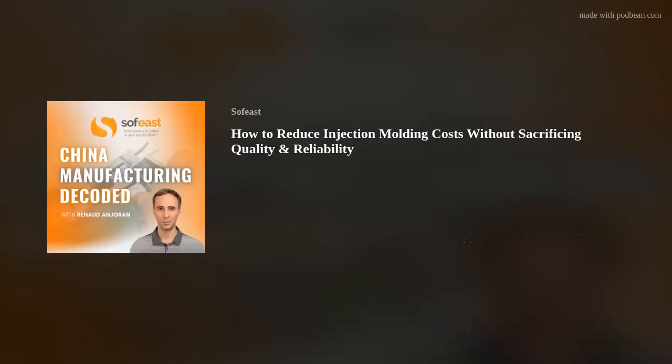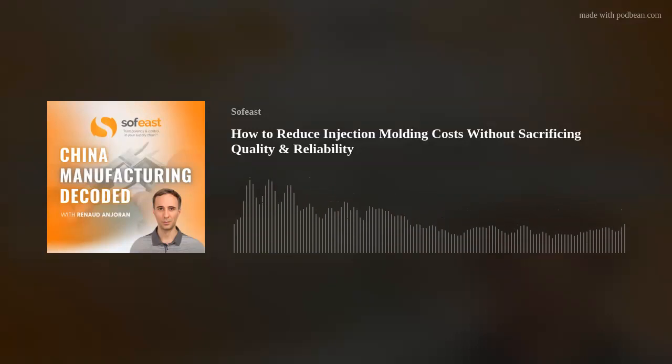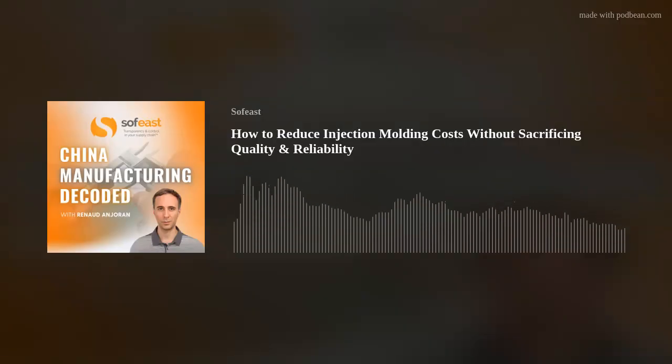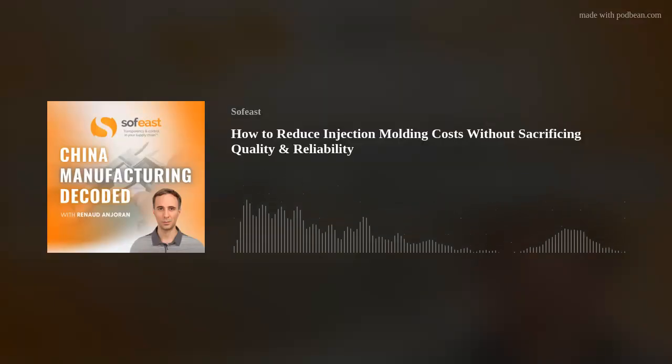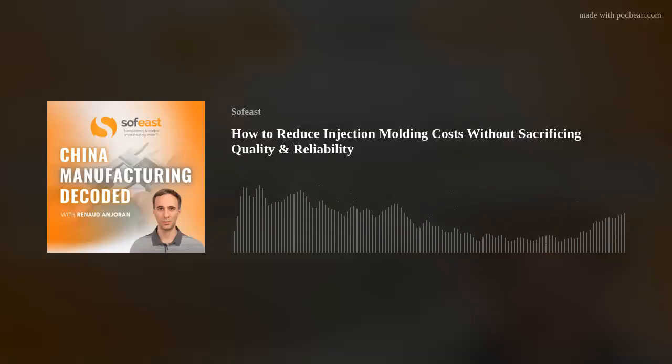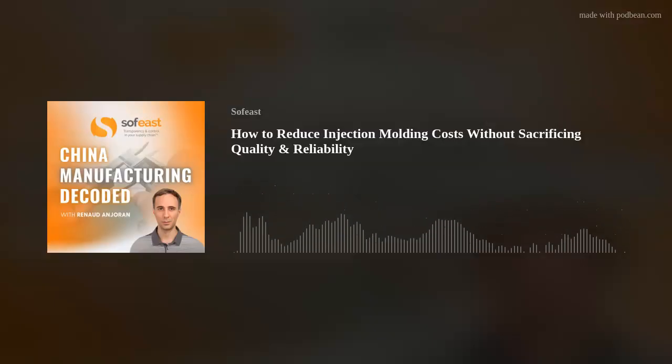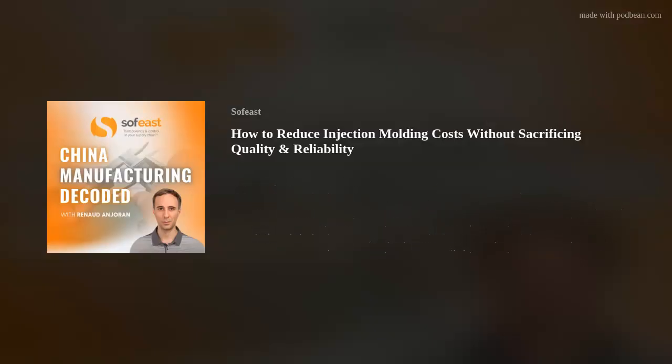If you are running a single product, same color, same process, invest in the hot runner. The hot runner is going to cost you a little bit more, but it's going to save you on material. In other words, your part cost comes down, but your tooling price will come up a little bit. But it's going to be so much more efficient, and again, it depends on the quantity that you require within your business.